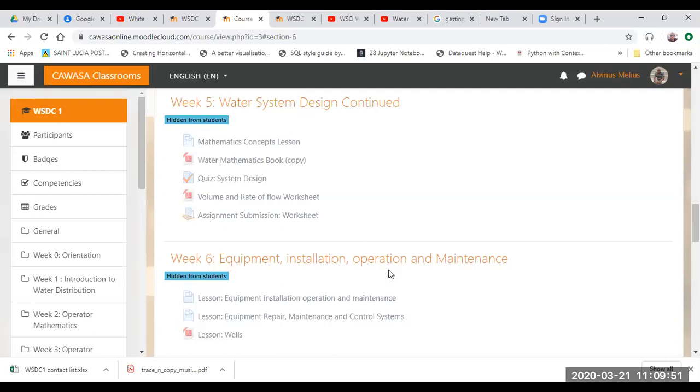Okay, Mr. Daniel is just adding a point here, which I think is very important. He's saying from a design point of view, your inlet, where the water comes in, should be opposite from the extraction point, where it goes out. Okay, so that would also help prevent stagnation.